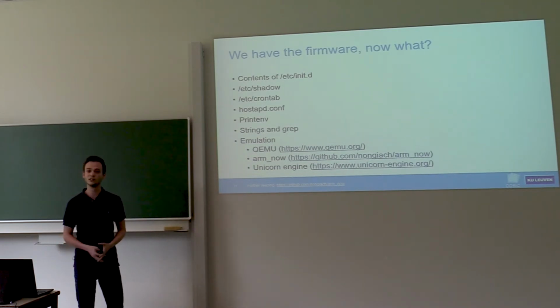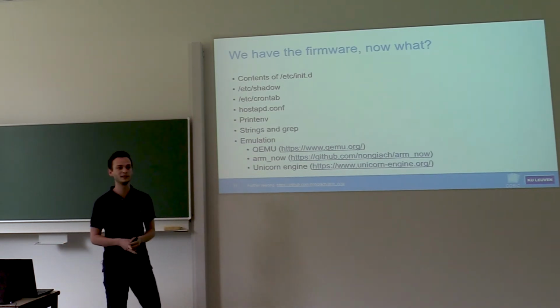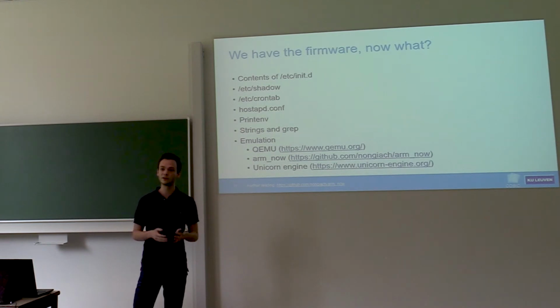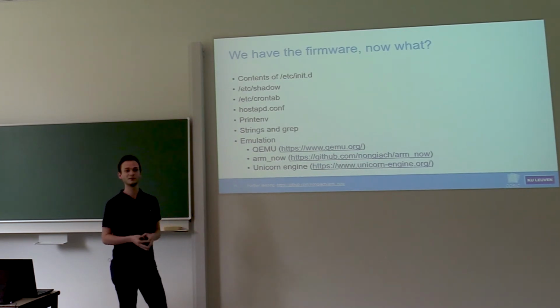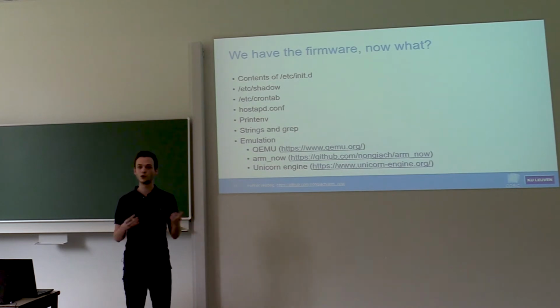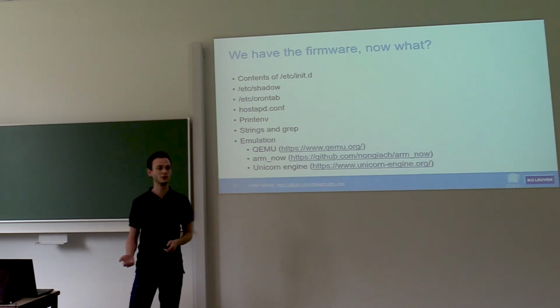Another thing to do is to emulate firmware. A lot of these devices have a web interface. So what you can do is use one of the emulators to emulate this web interface, and then you can not only interact with the web interface, so test the website like you would normally do, but you can look at the source code at the same time.